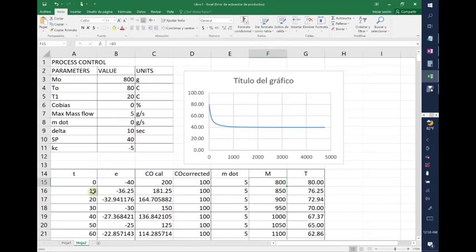So the next thing we need to do is go for the second line. Obviously, as you can see, this line has the automatic addition of the delta T, which is 10. Now we calculate these two values. These two need to be calculated by the Euler method, and it's pretty much identical to what we did in the dynamic case, except that the values here come from the table, including both the mass flow and the mass inside the vessel, which are these two values here.